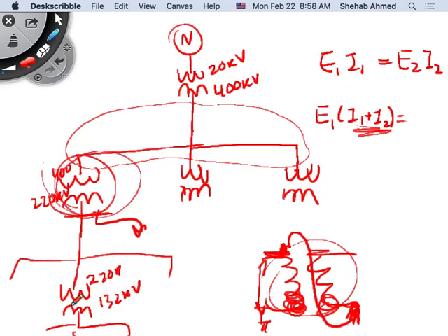Not very useful here, because here you're connecting to a customer. Here I'm connecting to Ras Laffan Industrial City. They want to make sure they're isolated from the 220 kilovolts so that they don't have to buy materials and equipment that is rated for the 220 kilovolt levels, for example. Otherwise it's more expensive for them in that case. So they would make sure that you are isolated.